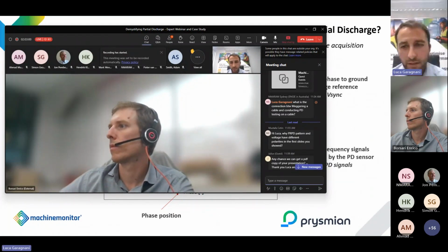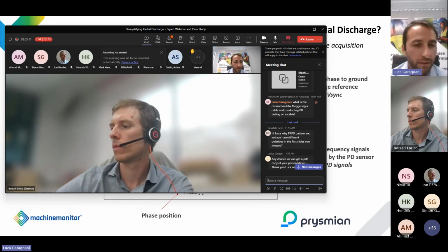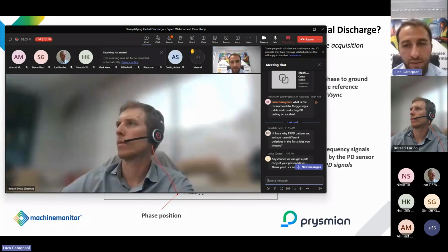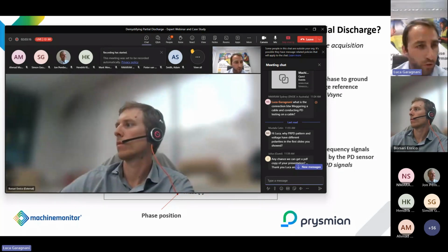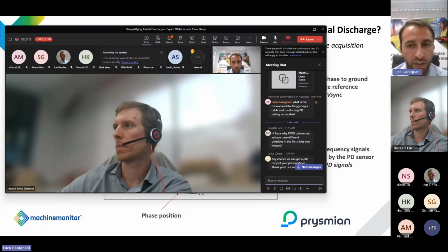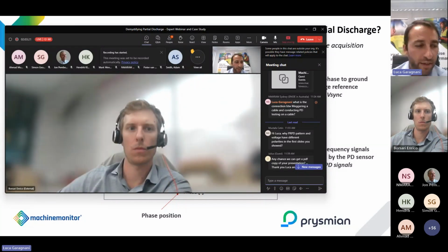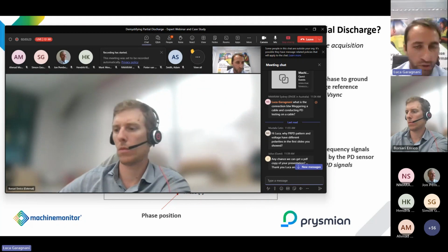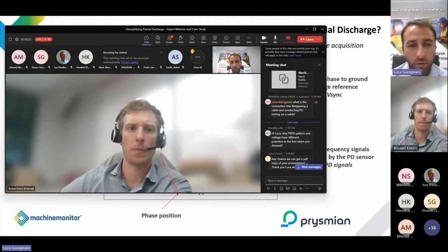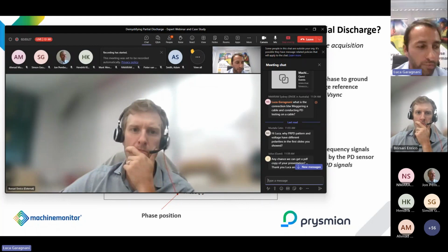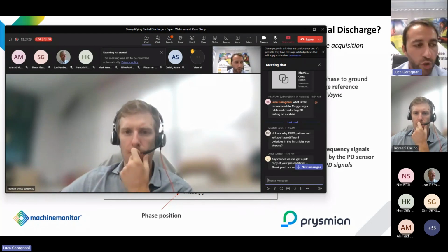Yeah, so that is a great question. So measuring normally is basically applying a DC voltage for 1 minute and make sure that the insulation is not too bad and you can energize it. So normally measuring doesn't give you much value in terms of diagnostics information. It will just show you that the insulation can be energized at high voltage normally. So when we talk about PD testing, we do more diagnostic investigation. So you detect the presence of possible defects.